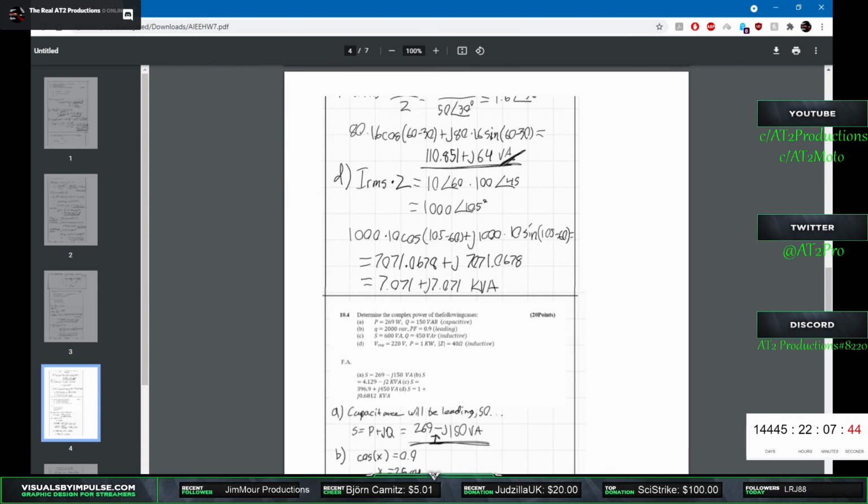So what was happening is after a good decel, the drive would latch an alarm on a DC overvoltage. And in order to clear it, you had to completely shut down and restart the drive. First time it worked.